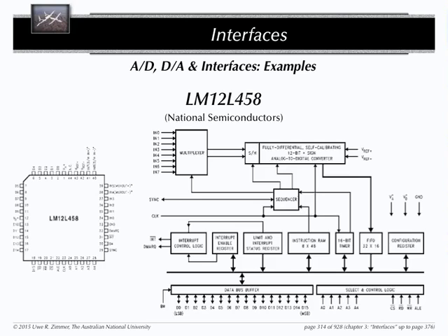So the FIFO register tells you that you have 32 words in that FIFO area here, but it's called FIFO for a reason. This is not a random access area. You can only pull out the latest reading out of this register. So this FIFO block here appears on your memory mapping area only as one memory cell.